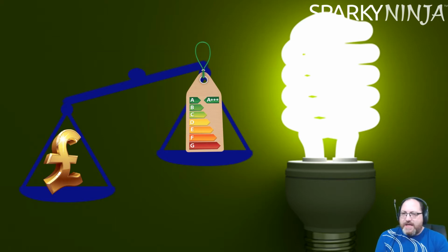So one of the recommendations now is going to be to consider increasing cable sizes beyond the calculated ones for energy efficiency. That's going to have a knock-on effect with cable selection and all of that stuff. But this is the kind of attitude that's being put here. That's what the barycenter method is all about, putting the actual supply and distribution centrally to make the runs of distribution as short as practicable, to obviously prevent any thermal effects and load shedding. But we'll see where this goes.